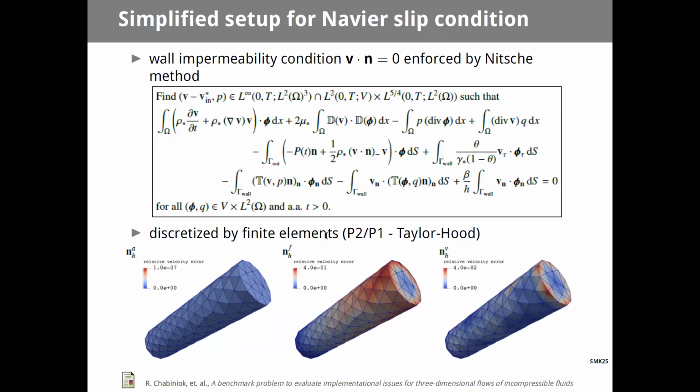And if you take simple Poiseuille flow, so straight pipe, do this implementation, actually you can compute the analytical solution for the slip boundary condition. So you can have an analytic solution, and here it is shown for such a mesh, depending on what kind of normal you take, you get very different results.